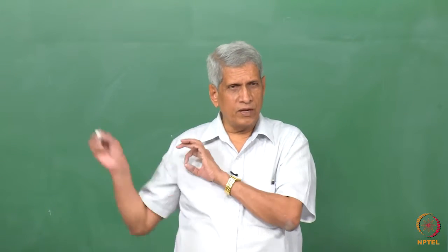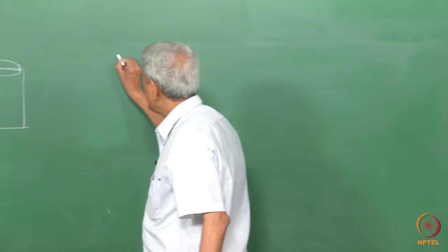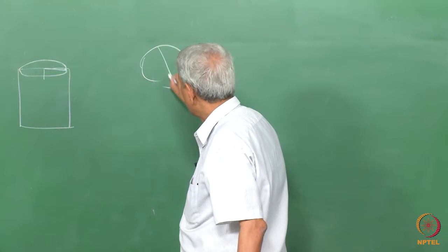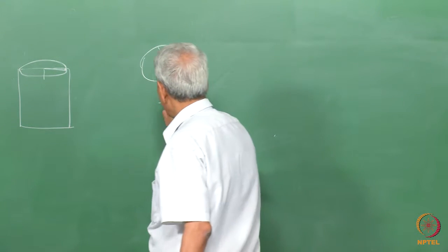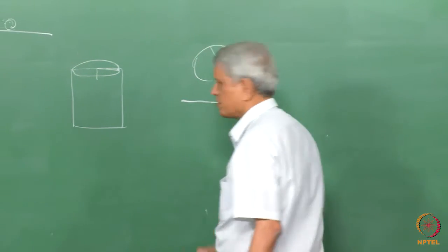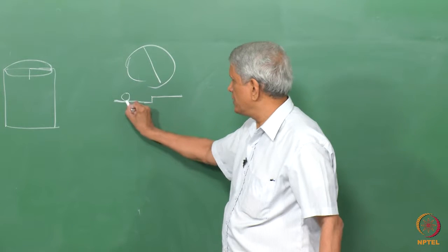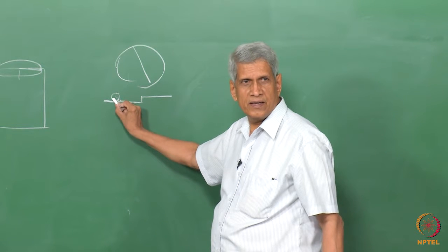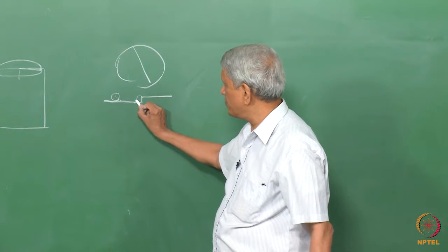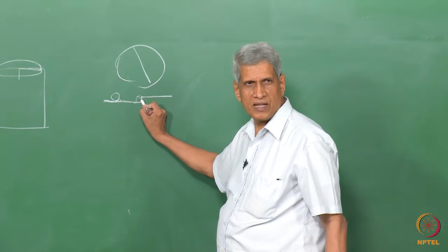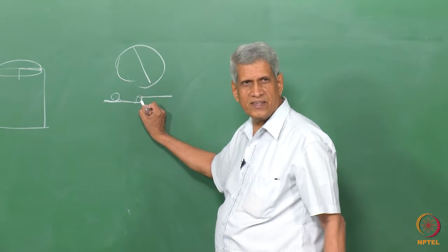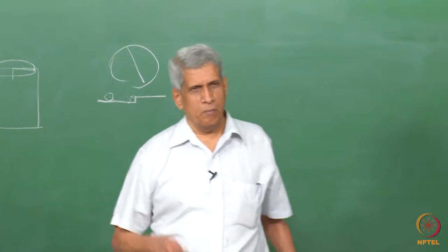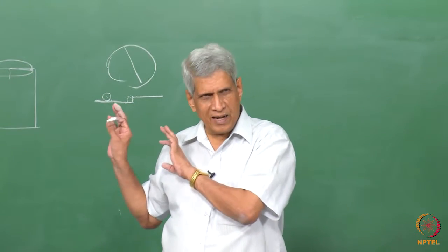Whenever there is a step present on the sample surface, like this sort of step, if an atom has to come and sit on this point, it has to make some number of bonds. If the same atom comes and sits here, the number of bonds becomes less. That means that at the ledge, it is easy for it to get attached. This is how they grow faster. Burgers vector defines nothing but a ledge.